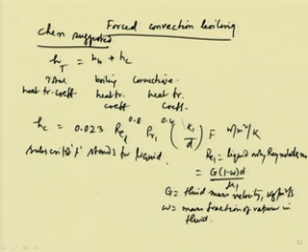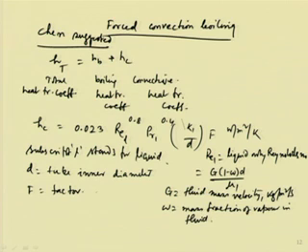We know that Pr is the Prandtl number, k_L is the thermal conductivity of the liquid, and D is the tube inner diameter. Now, the question is about k_L by D and F, and F is a factor. We will discuss these things. F is a factor, and then h_B, the relationship for h_B is given as 1.218. It's a very big relation.